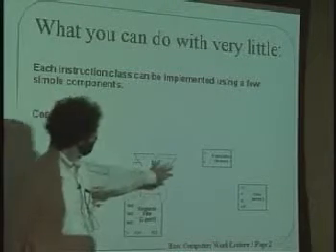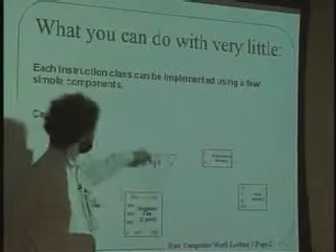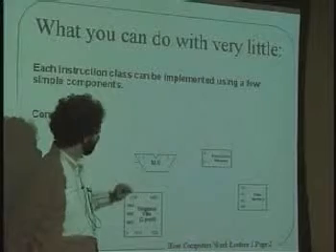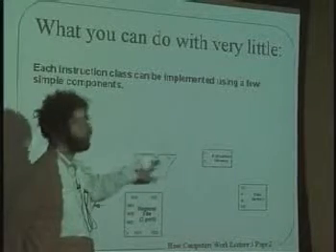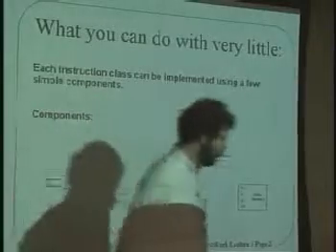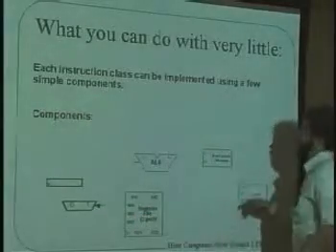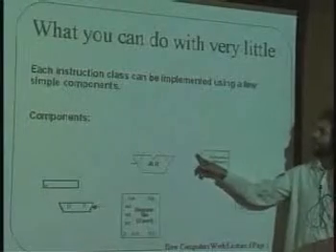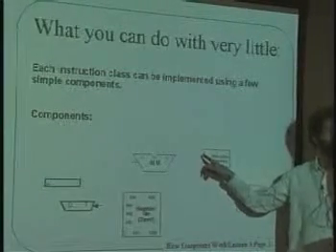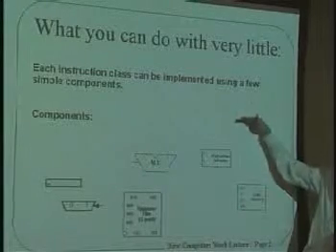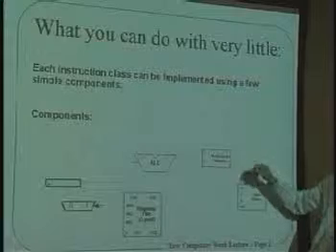We'll also have this arithmetic logic unit we've been talking about that's going to take an input A and an input B, and depending upon the computation we tell it to do, we'll do a calculation on the inside and produce a result over here. Finally, amongst the blocks that we're going to use is an instruction memory over here, and that will have an address input saying which address in the memory we want to access, and that again is how far from the beginning we want to read a particular word.